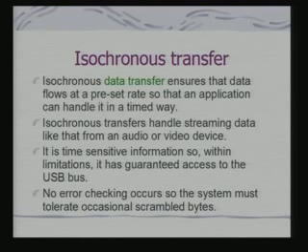If 1 or 2 bytes are scrambled in a video frame which is being displayed, it might not really affect the quality of the picture, or even there can be software post processing to take care of this kind of scrambled bytes. This is a very basic principle which we are discussing in the context of USB, but it is true for various other protocols which support isochronous transfers.